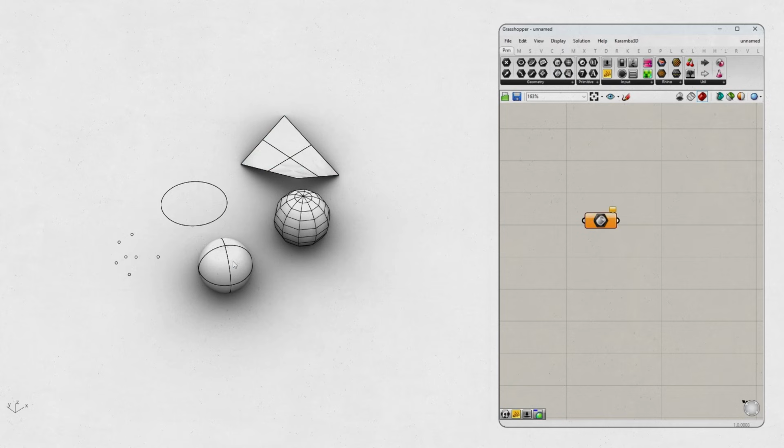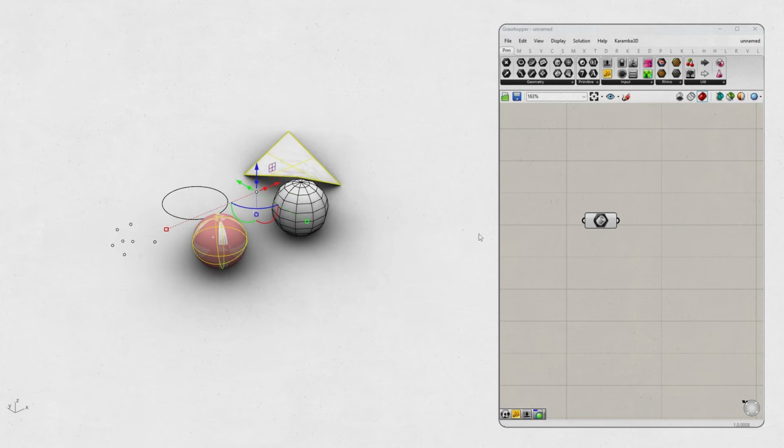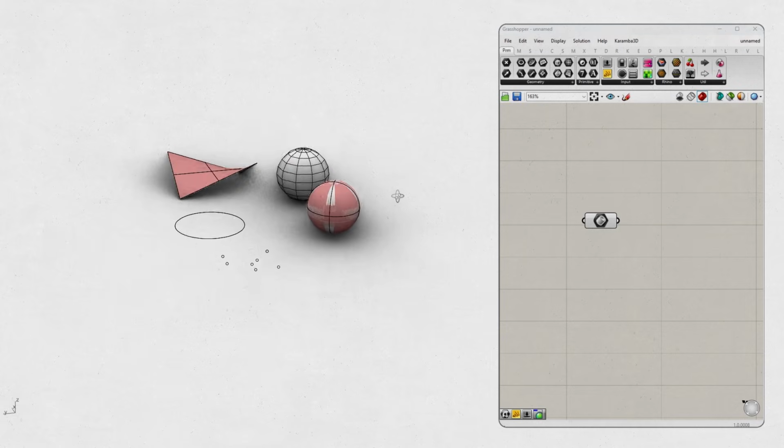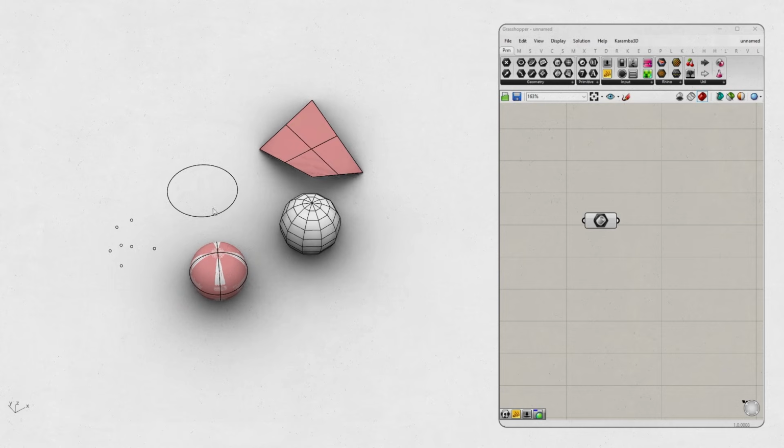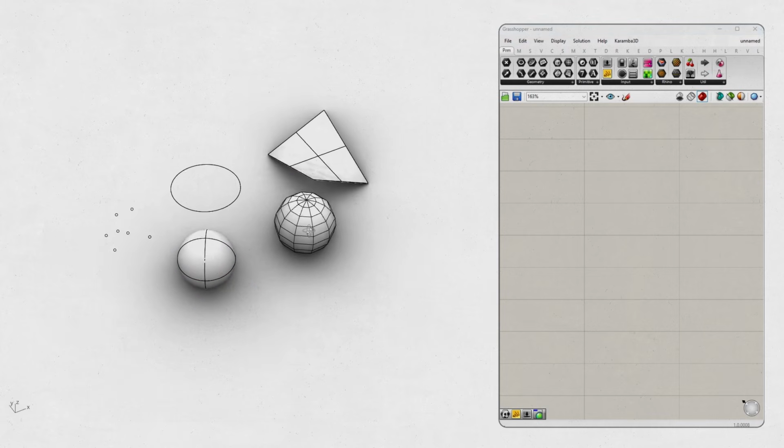BREP, right? It stands for boundary representation, and it's one of the most important components out there. This thing can handle complex surfaces, and it can also deal with open and closed volumes. So think about it like this. You've got examples like a cube, a cylinder, or even those intricate shapes modeled in Rhino. And don't forget about geometries made up of multiple surfaces. Now, here's where it gets kind of interesting, right? The difference between BREP and surface is super important. Surface is just a single surface, but BREP can be a whole collection of surfaces or a complete volume.